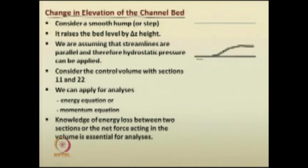You see here there is a channel bed. It has increased now at this location. Say, let this height be delta z. Initially the water was flowing at this level. Now, due to encountering this rise in bed level, we do not know whether the water level will increase, whether it will remain the same, or whether it will decrease. How will you analyze the thing?